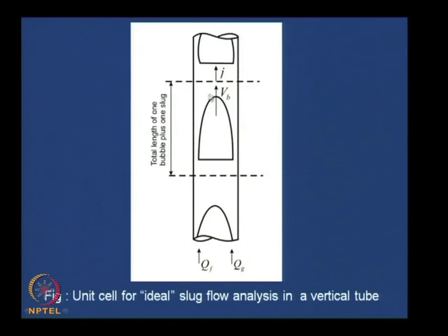Okay. So, therefore, we find that this rises up at a velocity ub, which is equal to ug, the in situ gas velocity. Now, at the bottom of the passage, air and water, or rather gas and liquid, are introduced at flow rates QL and QG. And these two phases keep on flowing up through the flow passage.